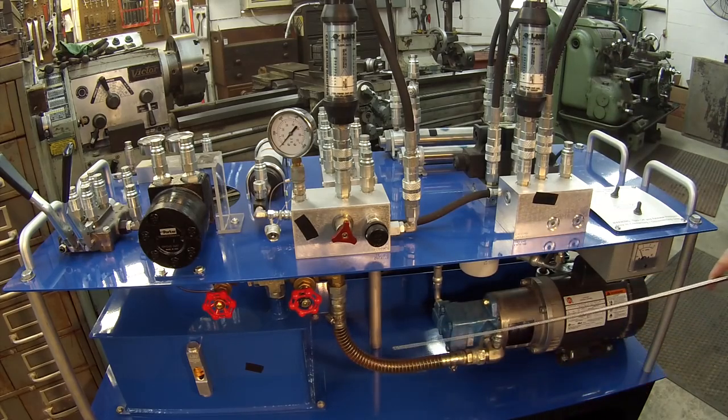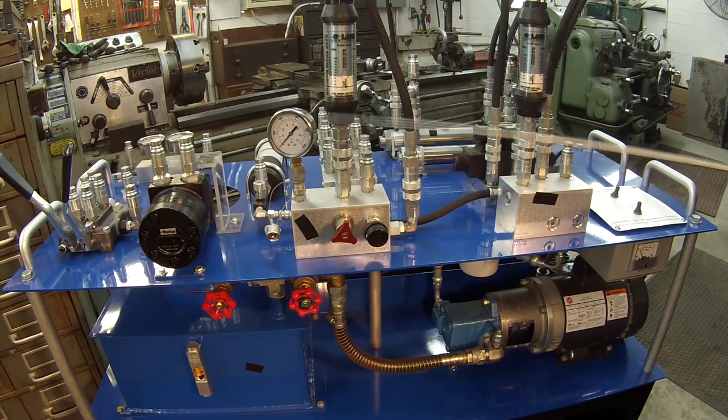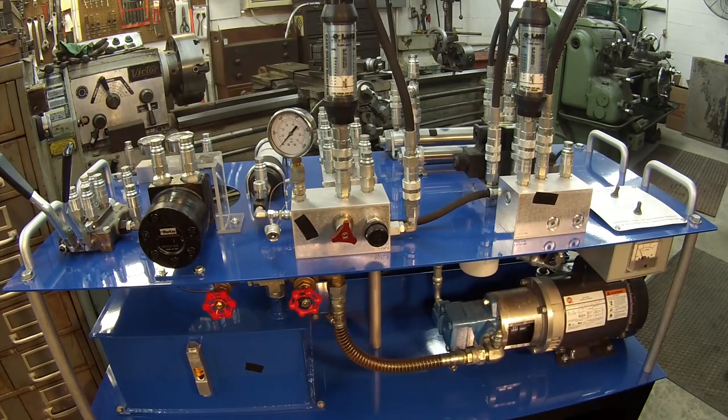Okay, so there's your inlet hose right there coming from your tank to your pump. Then you come out of your pump with this hose right here into this block here. Then you come with this hose right here into your directional valve. And here's your two work lines right here, your A and your B work line that go out to your hydraulic cylinder. And then here's your tank line that actually goes back through the filter to the tank. So that's the essential components of any hydraulic system in order for it to function, is those components right there.